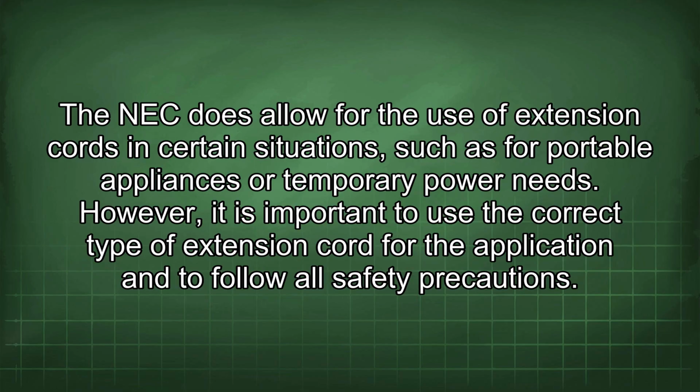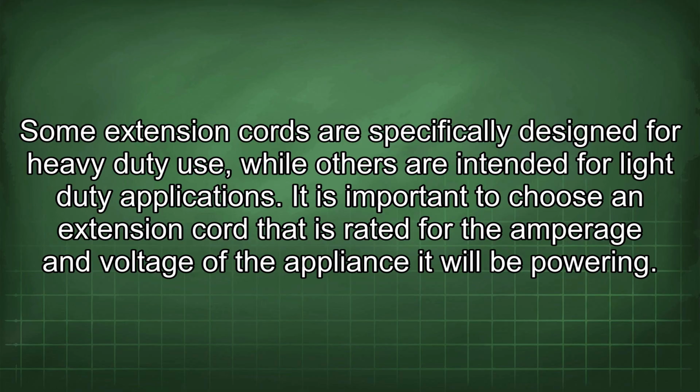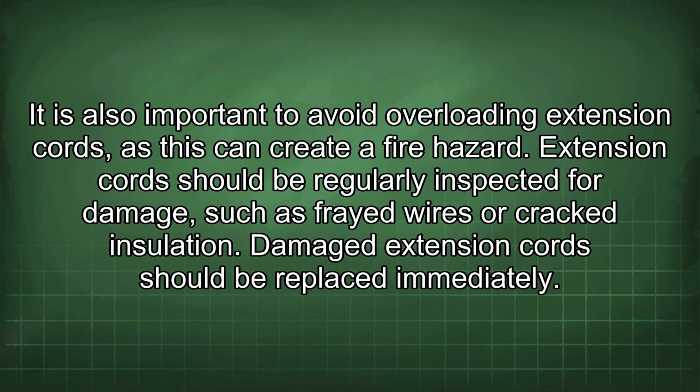The NEC does allow for the use of extension cords in certain situations, such as for portable appliances or temporary power needs. However, it is important to use the correct type of extension cord for the application and to follow all safety precautions. Some extension cords are specifically designed for heavy-duty use, while others are intended for light-duty applications. It is important to choose an extension cord that is rated for the amperage and voltage of the appliance it will be powering. It is also important to avoid overloading extension cords, as this can create a fire hazard.